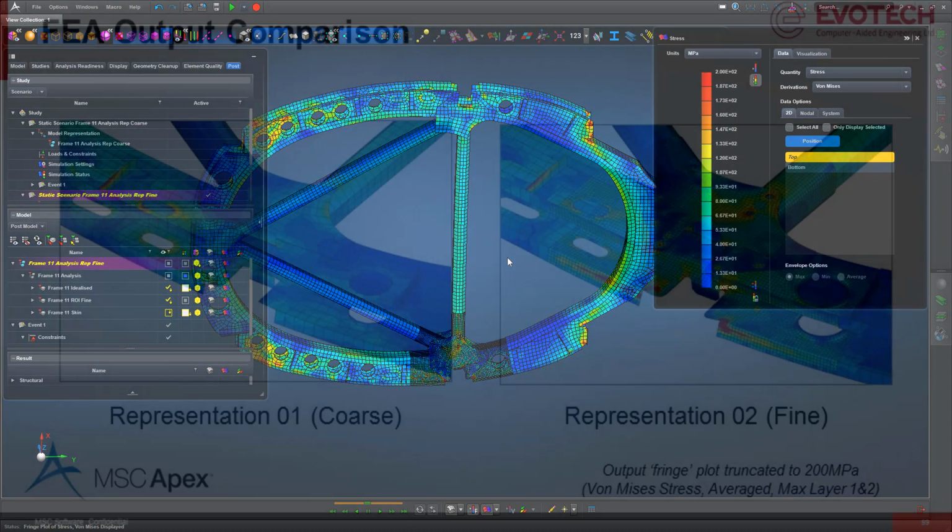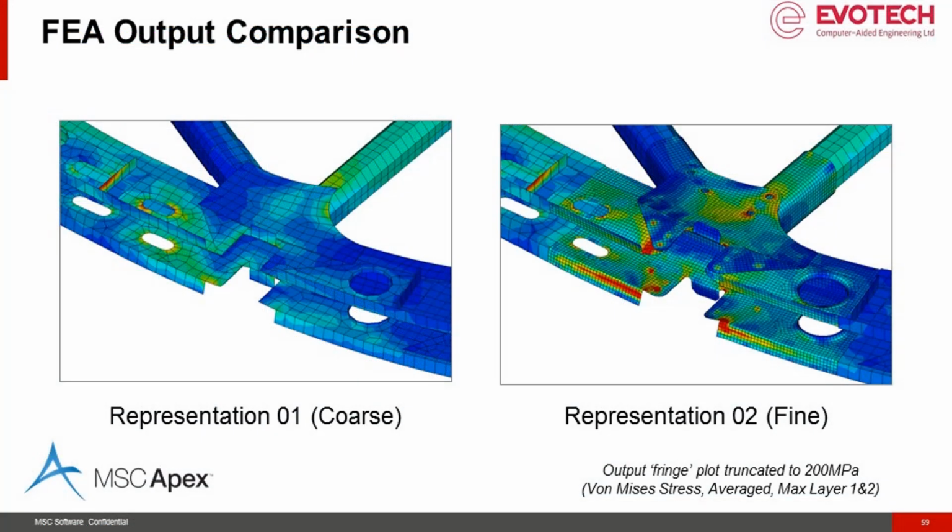So again, two different representations contained within the same model architecture. And depending on what we're trying to do, whether this is a loads model for screening, understanding load path, or a fine model for understanding detailed joint response and maybe fastener loads, bypass, or bearing bypass load between fasteners, we've got a good definition of that representation, and Apex is able to handle both model representations in a single model.